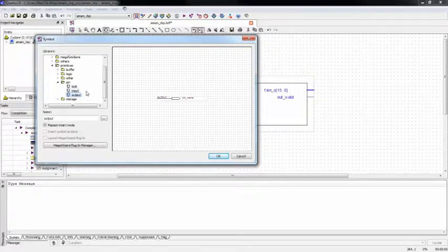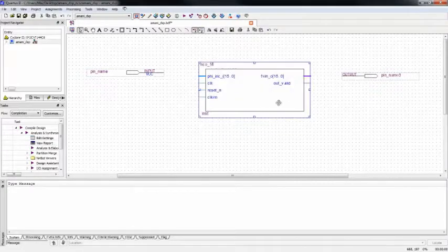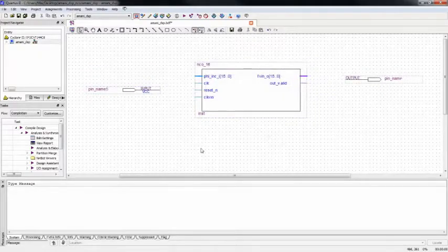However, we just want to give you a basic introduction to some of the DSP cores that are made available to you from Altera. So why we're connecting pins at this point in time is we want to use the SignalTap logic analyzer. That's also a feature of Quartus II, and it will actually connect to those pins and give you measurements of activity on those pins, and we'll get to that in a few minutes.